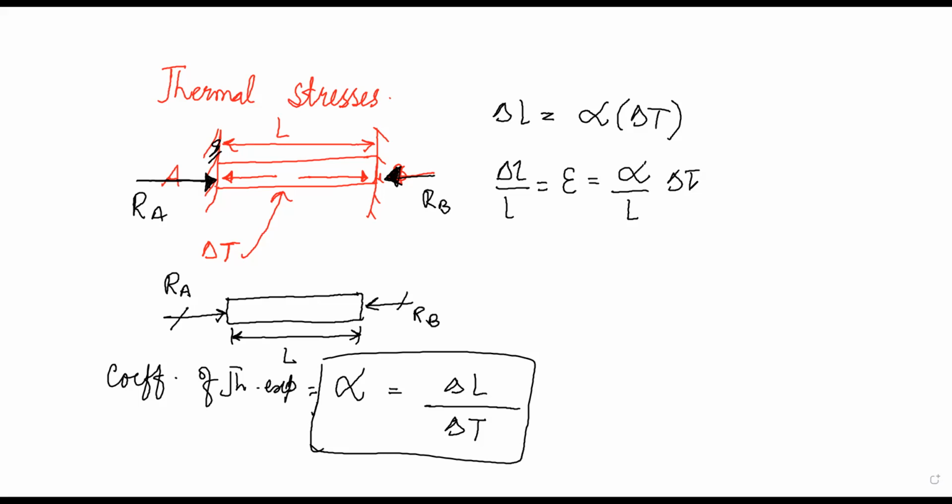We also know that stress is equal to Young's modulus times the strain. That becomes E alpha delta T. This is the value of the stress.